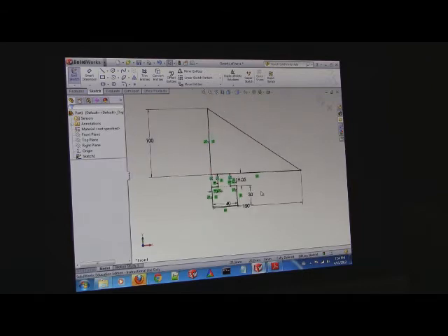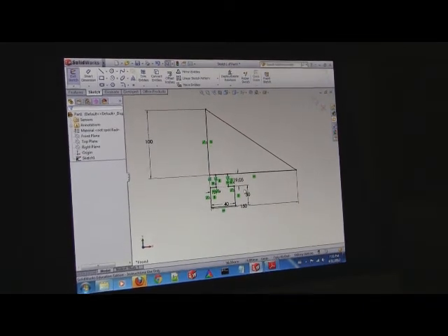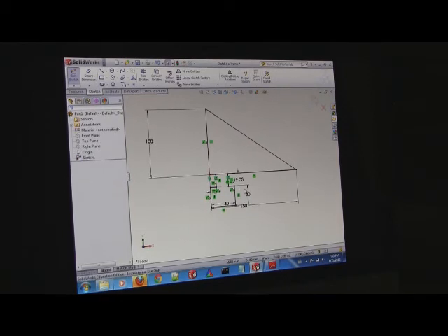Okay, does everyone's screen look like this? You did your line with the edge. Here, let me. Okay, who's having issues? No, stop doing that, Ruben, stop. I take control and do these two. No, that's a dimension line. See how it's thinner? Select the thick line, and that one, yeah, and now press collinear. Collinear lines the two lines on top of each other. Can I see for a sec? Yeah, on the right, on the left.